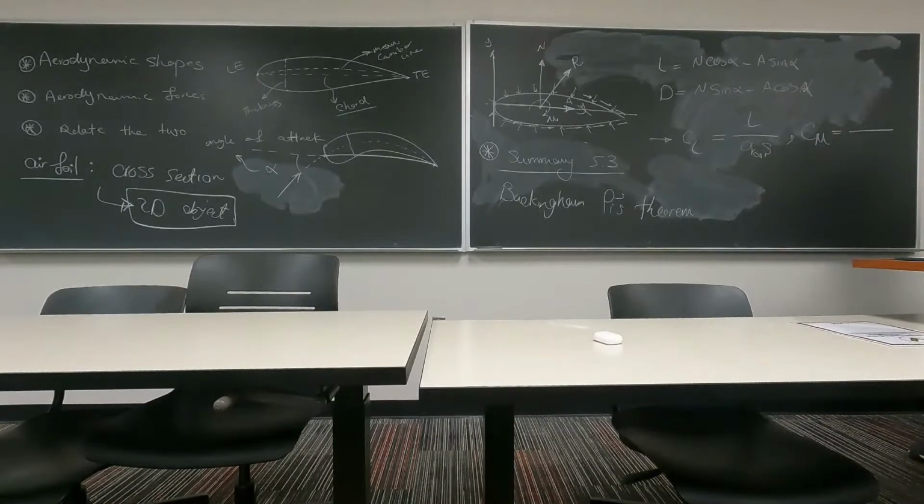Yes, S is on the top. Okay, but the units of this are newtons, right? So on the top we're going to have the moment. What is the unit of a moment? Newton meters. So if you divide these two, you're going to get 1 over meters here, and it's not going to be dimensionless. What should we do?